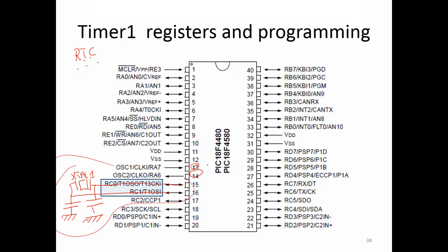When timer 1 generates an interrupt, it will wake up the PIC microcontroller, then you can do the task that you need. So in sleep mode, the whole PIC microcontroller will be asleep, except timer 1 with its external crystal. This is one of the advantages of using a second crystal.